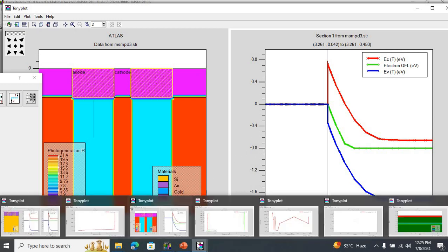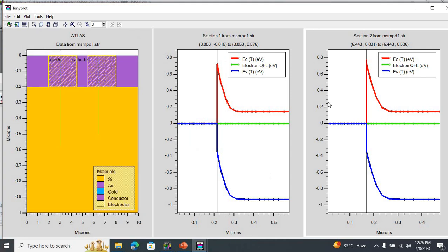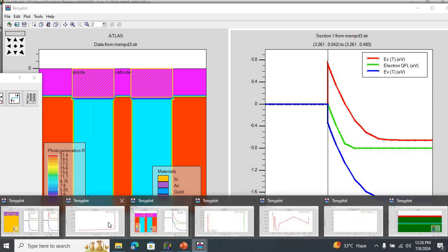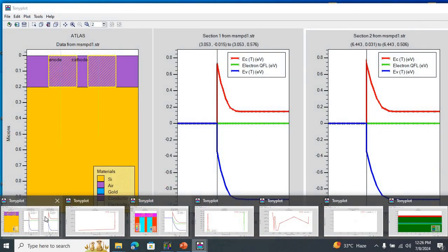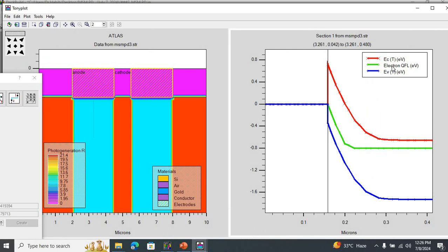If you compare it with the energy band diagram under thermal equilibrium, you might see that first of all, under thermal equilibrium we have a constant Fermi energy level. However, under reverse bias, the Fermi energy level is not constant anymore. Also, if you compare these two, we see that the built-in potential barrier on the semiconductor side has now increased under reverse bias.